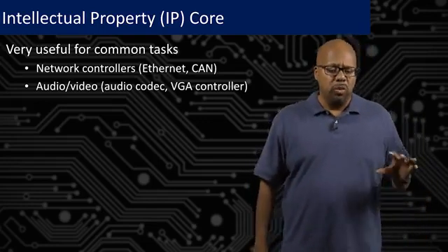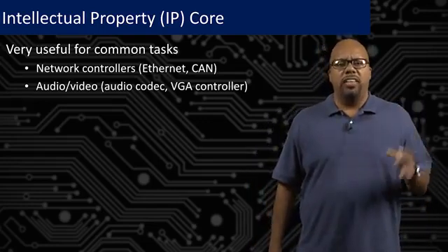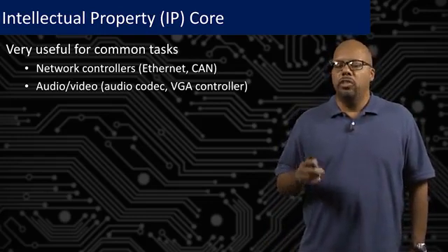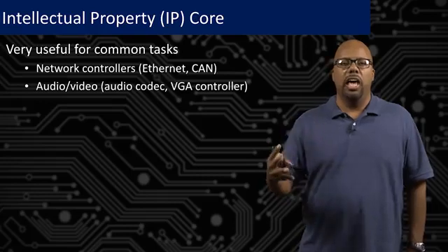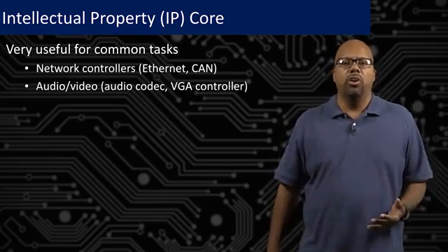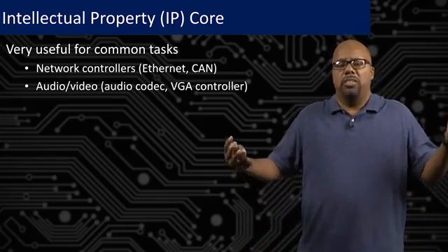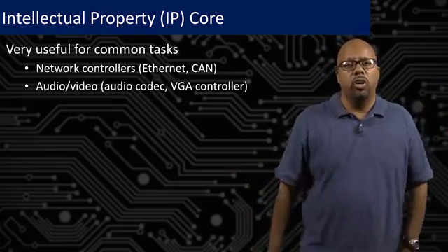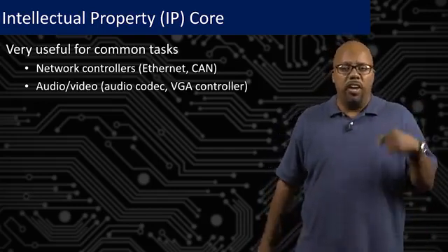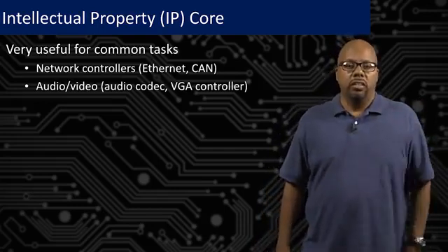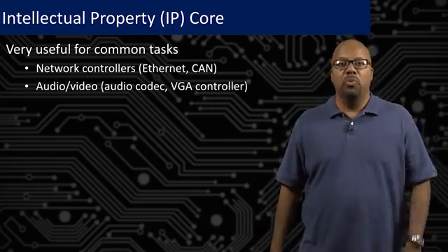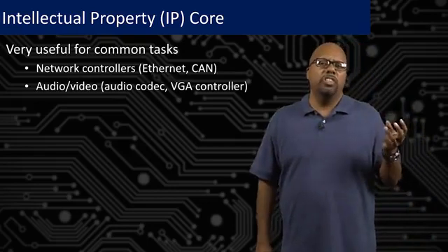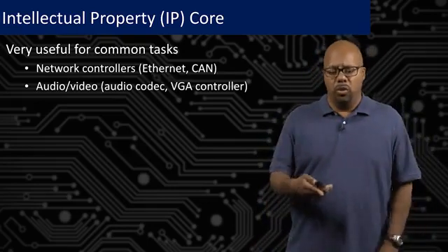Now these IP cores, we're not designing them in this class. That's outside of the scope of the class. But when you're making an IoT system, you definitely might want to buy one of these. So you'll look at an online library of IP cores, find some vendor, Texas Instruments say, they sell a lot of chips that do different things, and you find the one that does exactly what you want. You say, oh, I'm doing MPEG encoding. Let me find the TI MPEG encoding chip. And you'll probably find 50 of them, and you pick the one that you want, and that's the core that you use. So that's how we use these things. We're buying them off the shelf. We're not actually going to be designing IP cores because that's too complex.